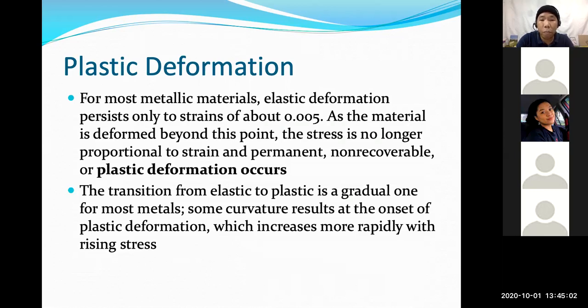The transition from elastic to plastic is a gradual one for most metals. Some curvature results at the onset of plastic deformation, which increases more rapidly with rising stress.